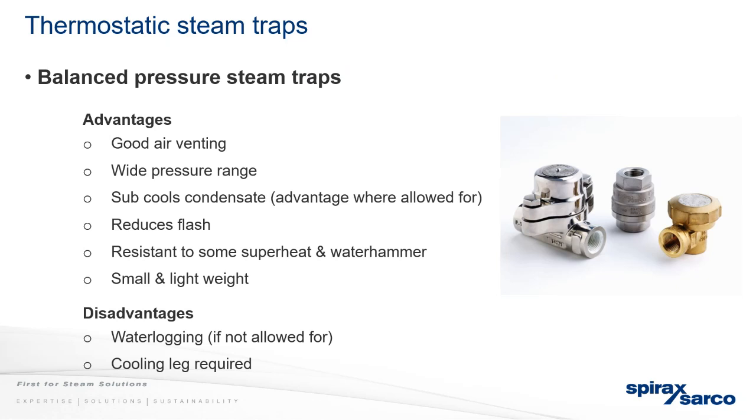No, not necessarily. I think it's a good explanation. It depends on the application. No, air vents high, traps low. That's generally the rule.